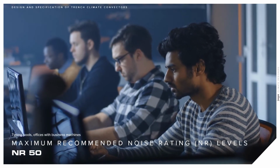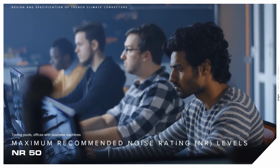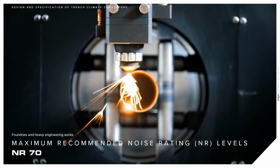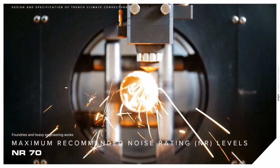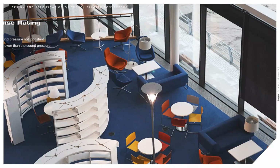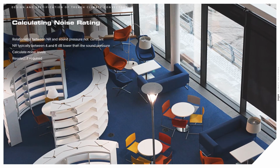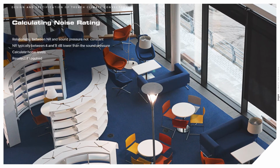NR50 for typing pools and offices with business machines. NR60 for light engineering works. And NR70 for foundries and heavy engineering works. The relationship between noise rating and sound pressure is not a constant. It depends on the characteristics of the noise itself.